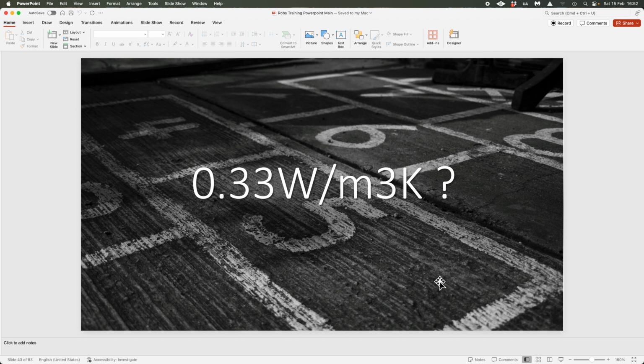So this is a constant. This is the third constant that we have. We had the indoor and outdoor surface resistances overall on the calculations on fabric heat losses. This now is the third and final constant that we would use. It's 0.33 watts per cubic meter, not square meter, per cubic meter Kelvin.